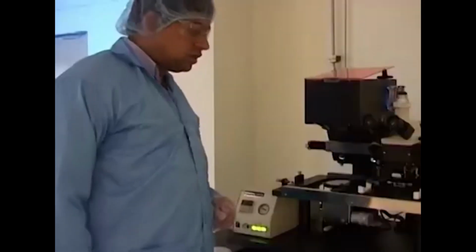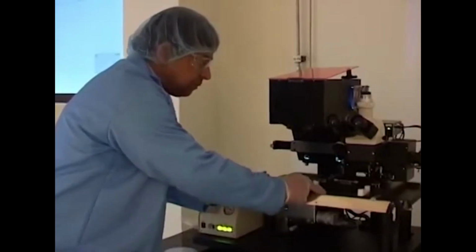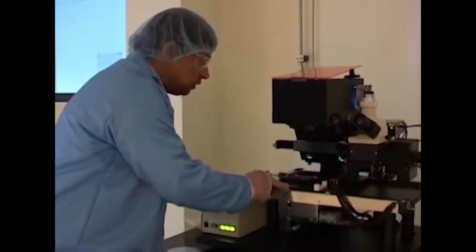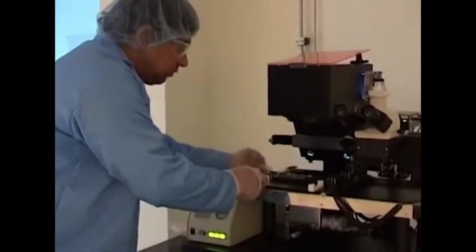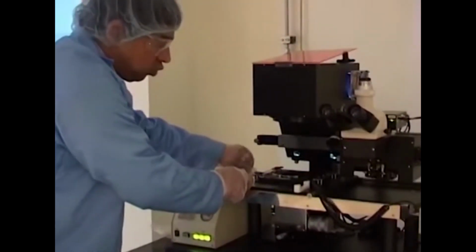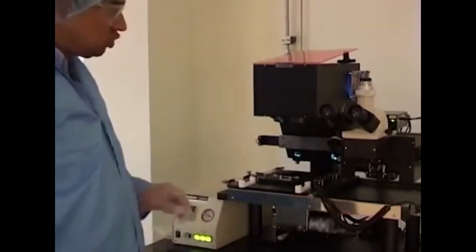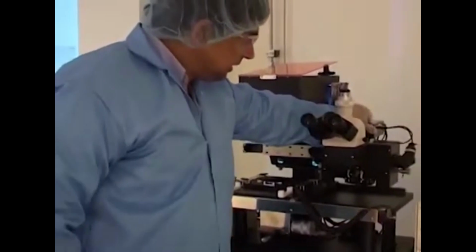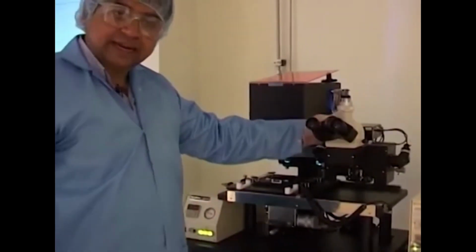The next step is exposure to UV. So in the next step, we align the mask with the wafer by pulling this stage all the way up to its location here, and then manually bolt the holder in this place so that it doesn't move back. Okay, and also what we need to do here is move this microscope stage back for the correct focus.